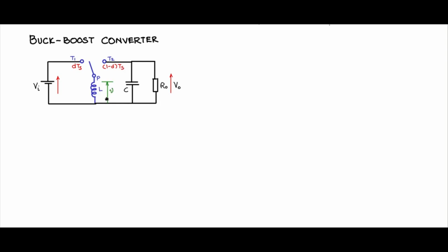We will measure the voltage across the inductor VL in this fashion. Common point here, measuring probe point here. I0 is as indicated here in this direction. IC is in this direction as we explained. IL current waveform, and now we shall plot the important parameters and try to understand the operation of the buck boost converter.